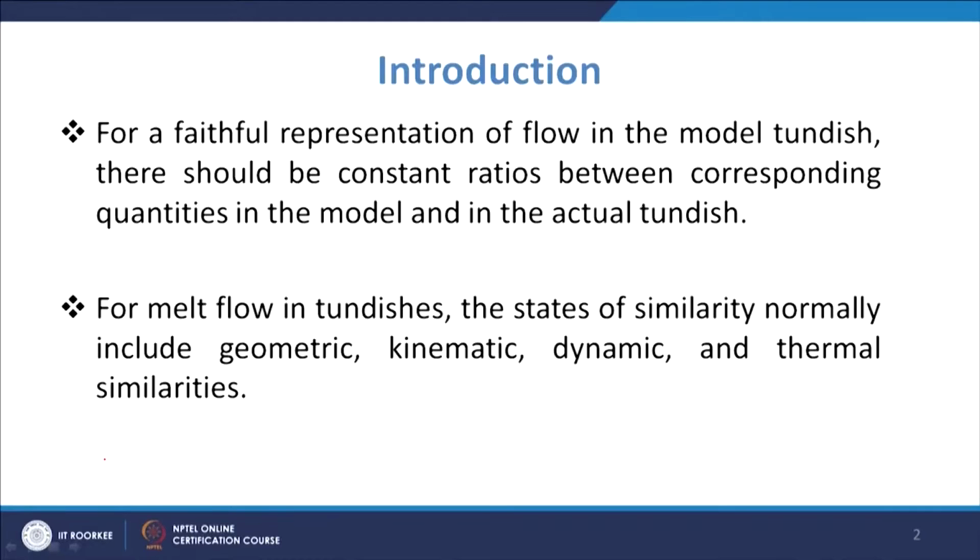In most cases the system involves the flow of species, flow of fluid, chemical reactions taking place, and heat transfer taking place. So, to predict these properly, you need to have the similarity principle satisfied. As we have seen, for the faithful representation of flow in the model tundish, there should be constant ratios between corresponding quantities in the model and in the actual tundish.